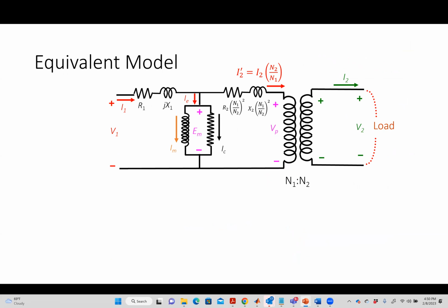Now the resistances here have the turns ratios in them like that. So I get the same basic thing. The thing that I've added here is I've got a voltage across this magnetizing component, so I've added a term there, but this is the basic idea of what you get, and you would hook your load up on that side. So you're basically getting the secondary all by itself. And again, it's not hard. If you want to prove that to yourself, do the KVL relationships, and you can see that sometimes we call that the T model. You can show that that's entirely equivalent.